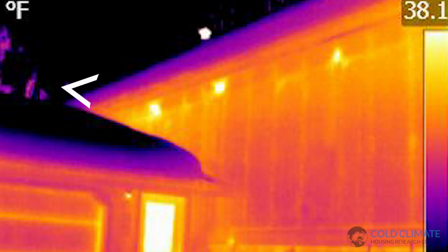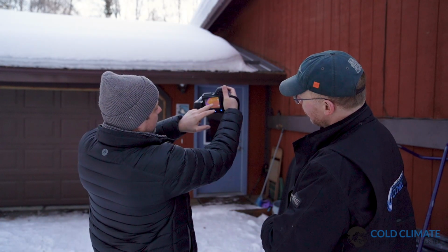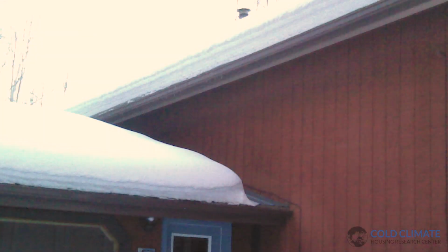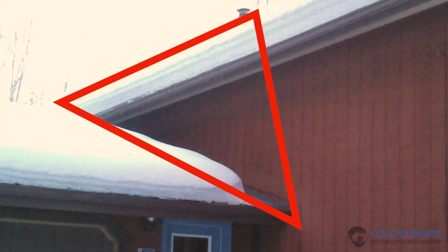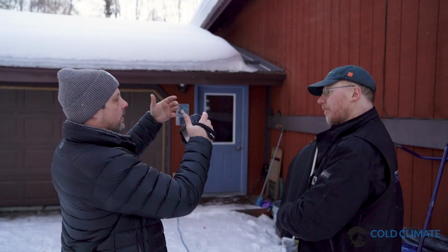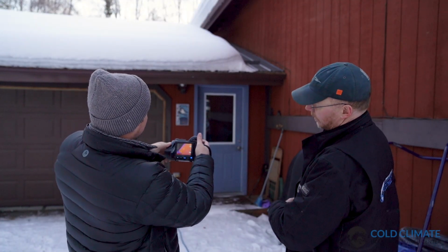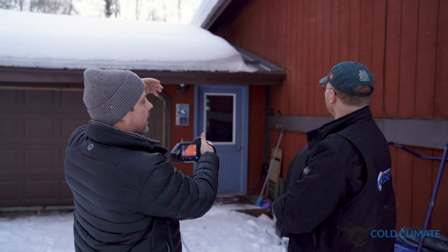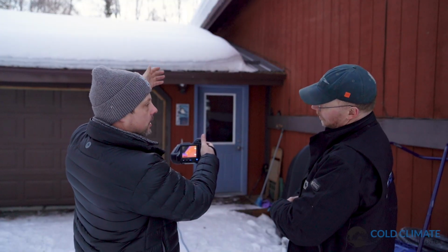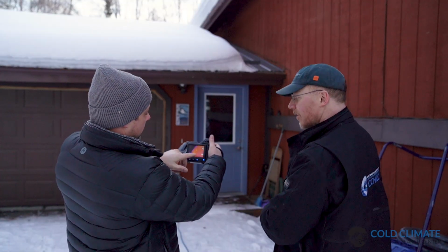We're seeing several hot spots at the top of the wall. Besides the 2x6 24-inch on-center framing, we see an increased heat flow out of that wall section. And it occurs because we don't have exterior sheathing inside that attic space. You have exposed fiberglass, increased convection through the insulation, and that heat just starts generating and increasing up through the wall and accumulating at the top of the wall. You add in plumbing walls, you add the tub surrounds that are exposed on that attic space, and you get a lot more increase in heat loss